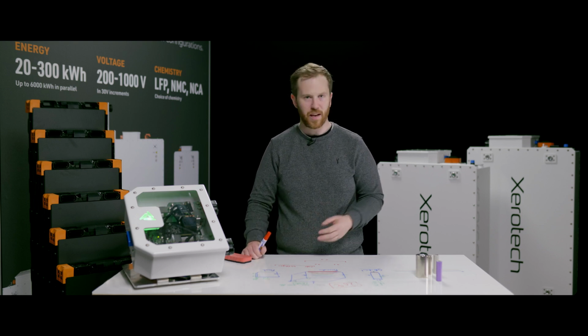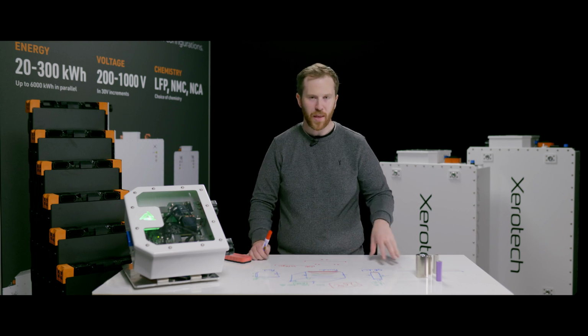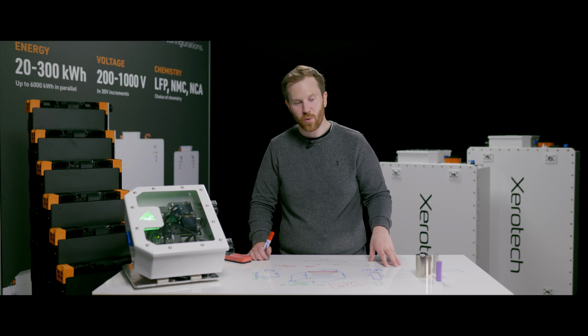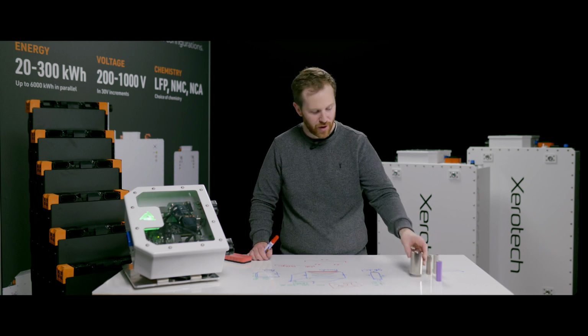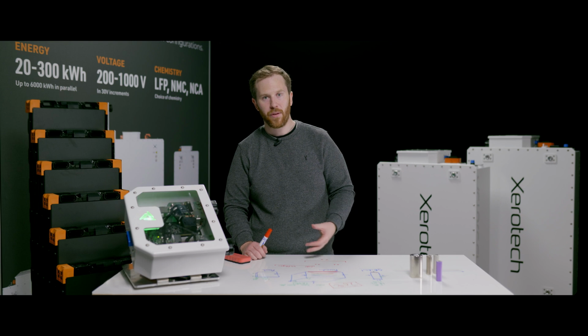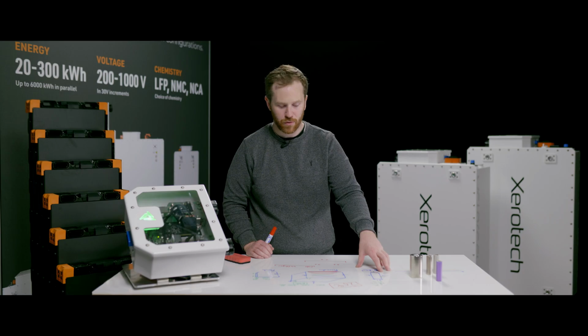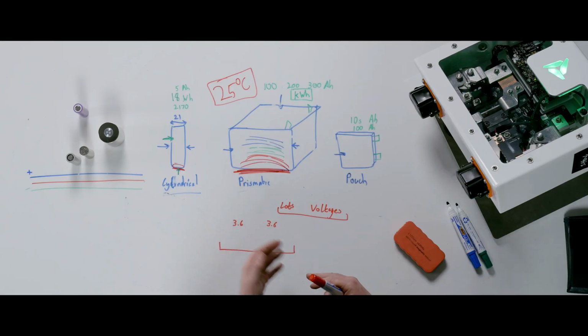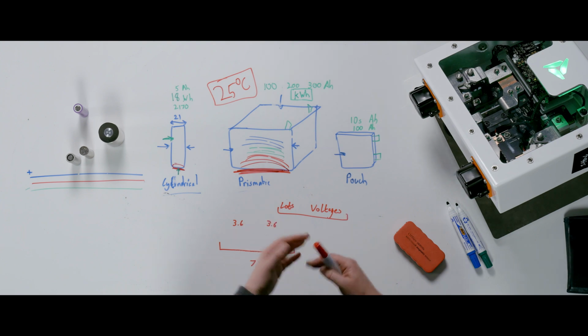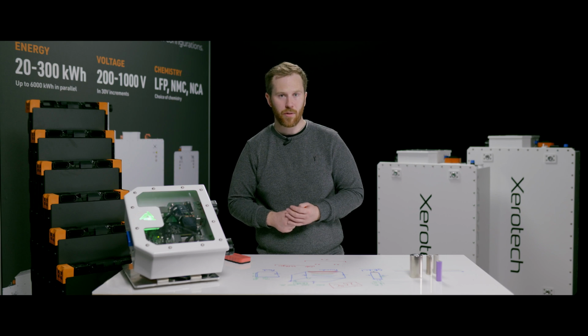These would be well-known names like Tesla and Rivian and Lucid. They all use cylindrical cells, usually 2170. They're now moving to 4680, many of them. And a lot of those companies have heritage from the Tesla pack design. And it's largely a good design based on some of the reasons that we've talked about here. In a European context, it's largely speaking a pouch-based design in the automotive manufacturers, also some prismatics as well. And then as you go to China, the other major market, it's dominated by large prismatic LFP and now NMC suppliers, dominated by the well-known major battery manufacturers.